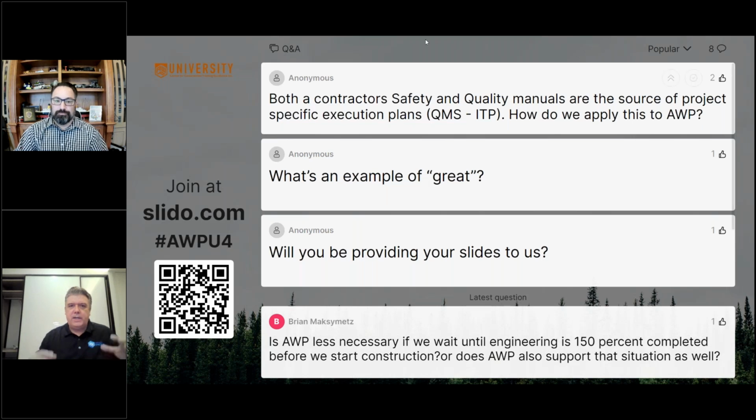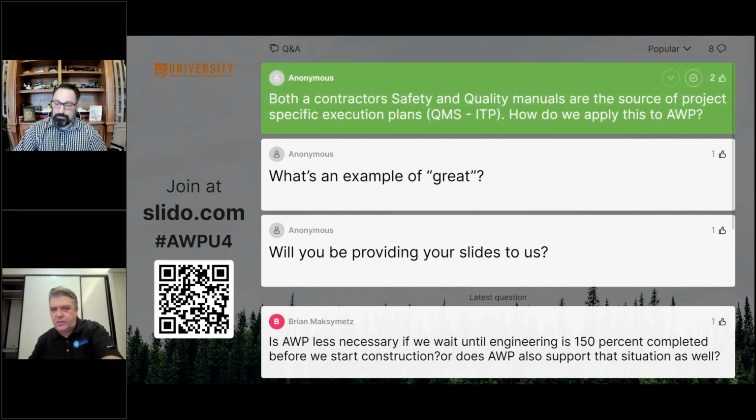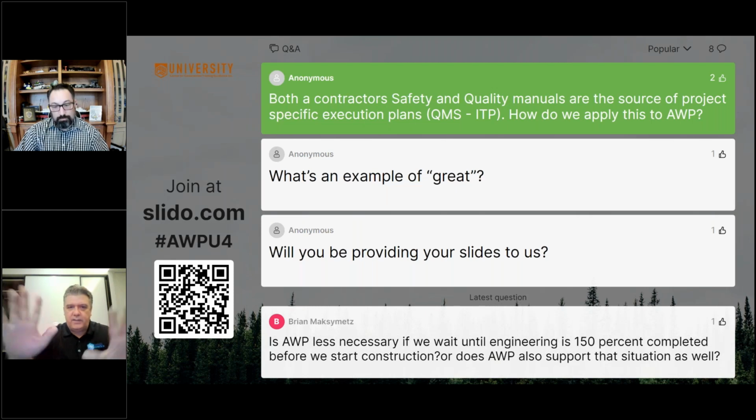Fantastic question. And as we are automating work steps and our generative AI is saying, okay, I've got work steps, request for inspections. So you should not be embedding all of the inspection content into the IWPs. They can be dynamically and largely automatically linked, where certain work steps trigger inspection hold points, or at the end, inspection request. And then the IWP completion could have construction progress complete versus certified progress complete. And there's not just a done, there's a done.